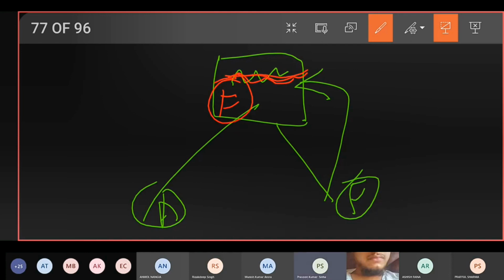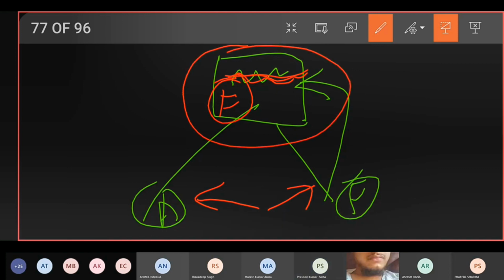So you have a switch. You can select the aft or you can select the forward transducer. Whatever you select, that recording will be shown on the recorder. The recorder should have clear-cut indication which depth you are reading. So as it changed over the switch, there will be some marking on the paper that now from this point on, you are reading aft draft or aft depth, UKC, or when you change over to forward, it will clearly indicate that this depth that you are reading is forward depth.